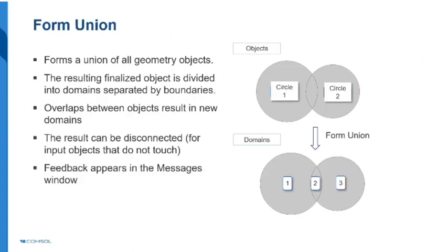First, when you are finalizing the geometry, the point which is closest to the origin will be numbered as 1. It will first get the distance for all the points present in your geometry, and the point closest to the origin will be numbered 1. From there, it will start numbering: the next closest point as number 2, the next closest as number 3, and so on.